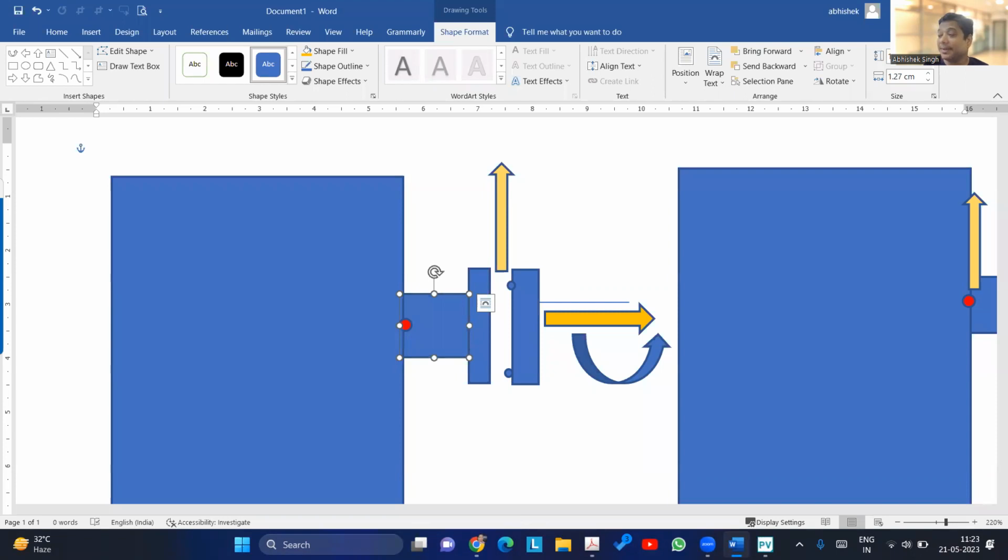You can reduce the pipe load by suggesting that piping use bellows, or provide support to that pipe, which will reduce the external load. So that is also possible. In that case, we provide the maximum load which my nozzle can take, and then piping will ensure that your loads are not exceeded. That is also one option.